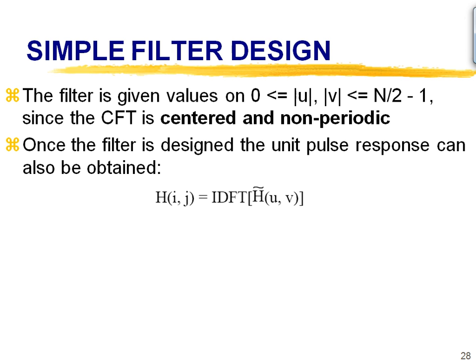So in fact, it is not an isotropic filter. An isotropic filter simply means that all directions get the same property of the filter. All frequency orientations are affected similarly. So obviously in a two-dimensional space, if we want an isotropic filter, it typically has to be something that's circularly symmetric. So a circle is an isotropic filter, a square would not be.